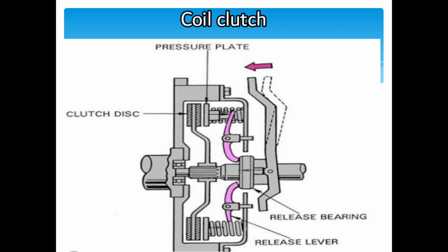If we ask, what causes AC clutch coil failure? I think the most common cause of compressor clutch circuit fuses blowing is a compressor clutch coil having a resistance value which is too low. Taking an ohmmeter and checking the clutch coil resistance will quickly tell you the resistance.